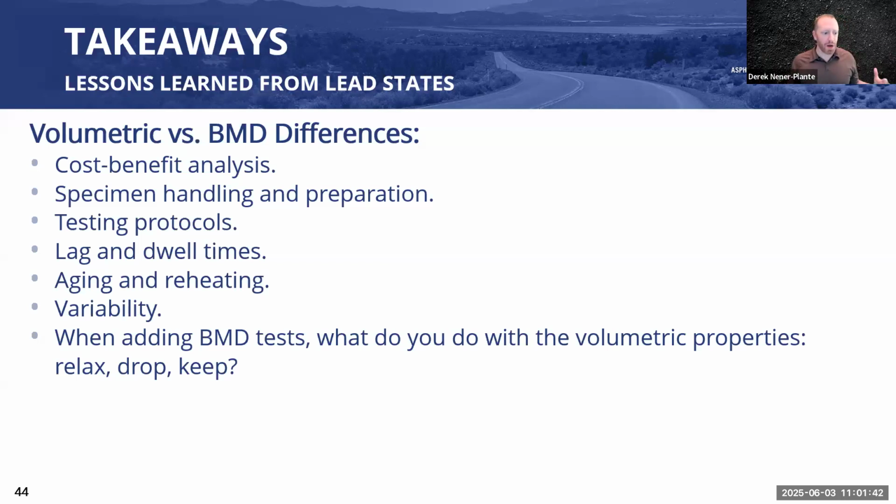Certainly, those of you who have heard me talk about lag and dwell times, right? The amount of time that a sample or specimens sit on the counter. Often this has to do with reheating specimens, but if they sit somewhere for a while, does that change it? A lot of that work is ongoing through CAPRI, et cetera. That has impacts here because that's telling you how to match up between a contractor and an agency, or if there's a dispute situation, right? All of these are differences that we may not have to worry about for asphalt content necessarily. Maybe with CT index, we will.